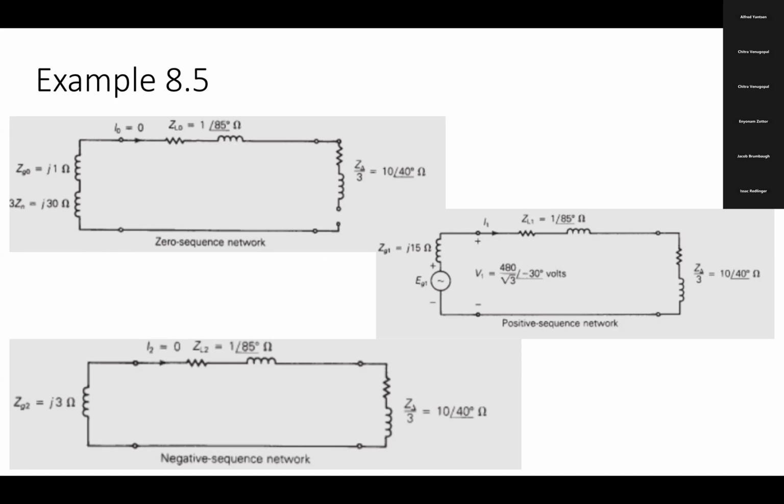Oh, okay. So Tom's question is about the impedances. We talked about the current, right? Current is going to go in three different phases: one is a subtransient current, another is a transient current, another is a normal current. For generators, we used to put Xd double prime, Xd prime, and Xd. So the subtransient phase of the current is usually the current that we look at in the positive sequence.